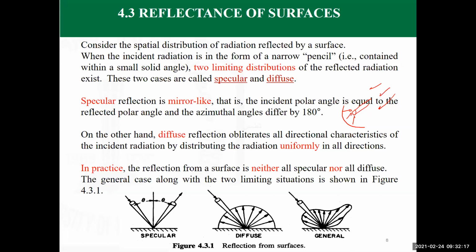The higher the solar energy intensity, the higher the electric power that you get. But the higher the solar energy intensity, the hotter the surface gets. And then when the surface gets hotter, its efficiency decreases. So they started to come up lately with something that they call PVT panels. They have panels which are basically PV, and in the back of the panel, there are channels for water to pass. What does water do? It cools the panel, so the panel temperature does not exceed a certain value, so you keep its efficiency. Meanwhile, you are heating the water, because as the water absorbs the energy, it gets heated. So you are making benefit of both.